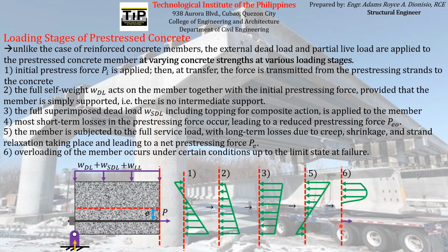Those tensile stresses will now be resisted by the pre-stressing reinforcement and the steel reinforcement themselves. Together with that, the remaining portion of the concrete element will still resist the compressive stresses, which will act on the cross section together with the tensile force acting on the pre-stressing reinforcement and the steel reinforcement. So this is the stress diagram that will act on the concrete element at ultimate stage, at impending failure.